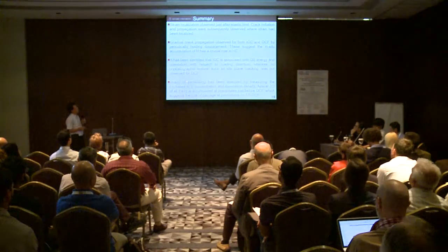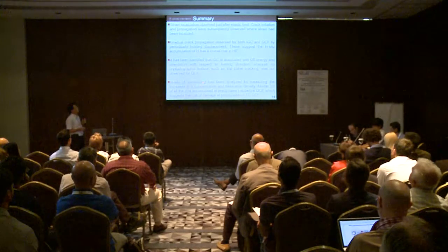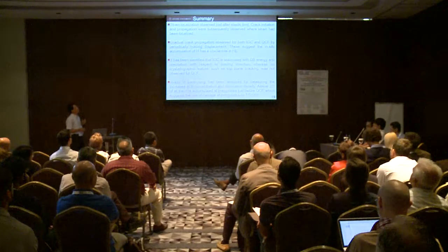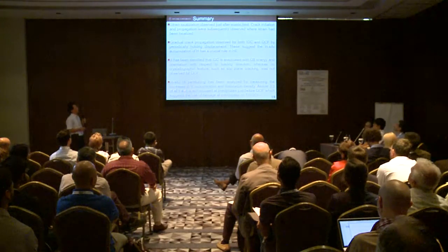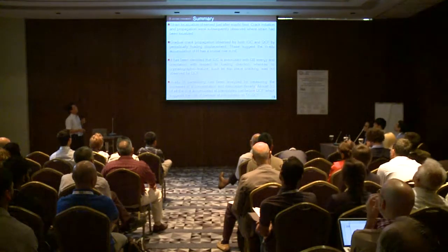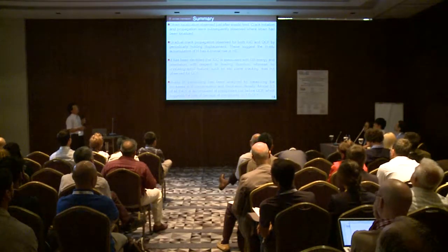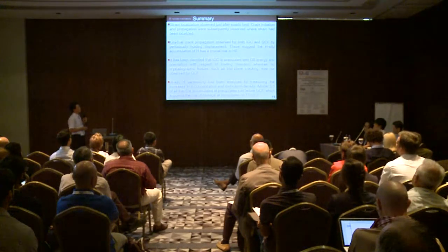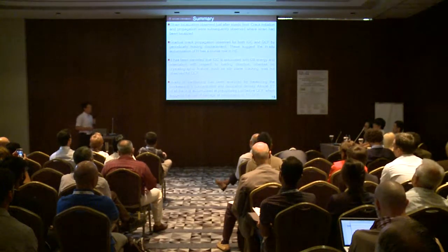And in situ hydrogen partitioning was analyzed by measuring increase in vacancy concentration and dislocation density, and almost 2/3 of all the hydrogen would be accumulated at precipitates just before quasi-cleavage fracture. And fundamentally, the quasi-cleavage fracture of aluminum alloys was non-crystallographic. Thank you very much for your kind attention.